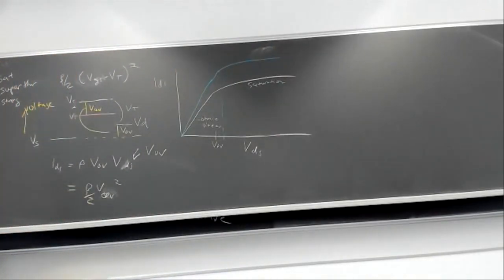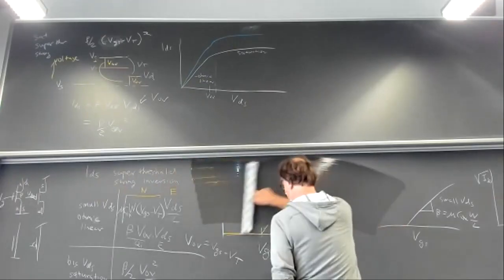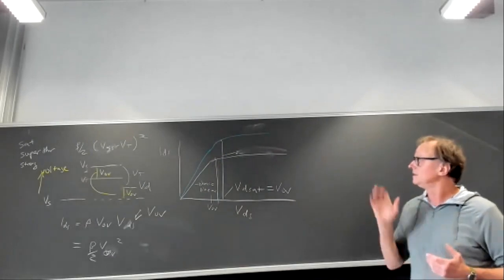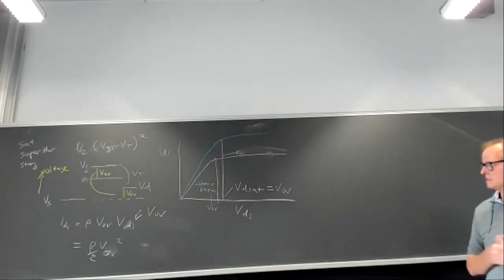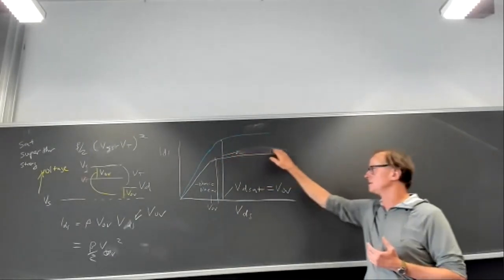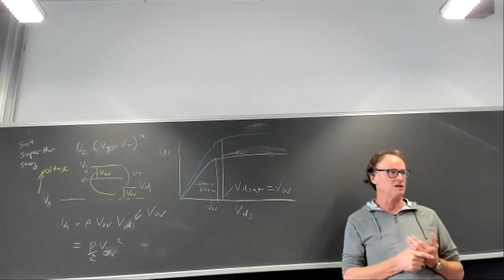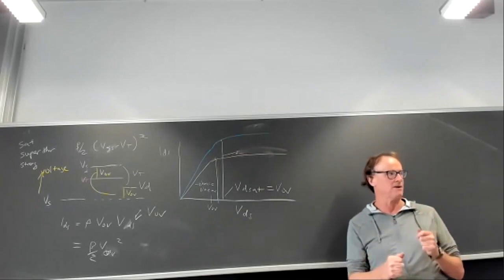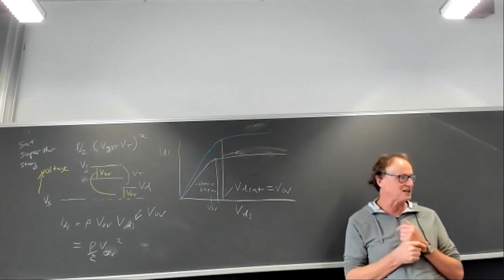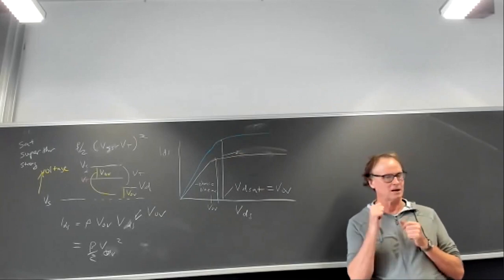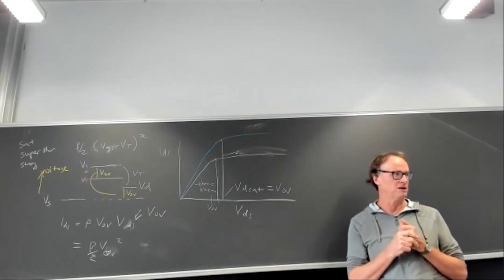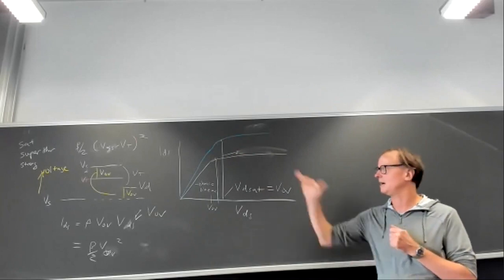But I have to explain one more thing, which is drain conductance, because you're also going to measure drain conductance. This is important that you see this, but you need to have a mental break of 5 minutes. Okay. So what I haven't talked about is what happens out in the saturation region. That's an extremely important region of operation of the transistor because in most amplifiers you build, the drain is going to be saturated. And the current should not change with drain voltage, but it does.